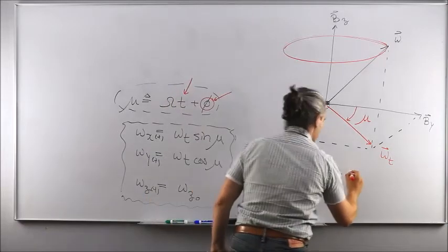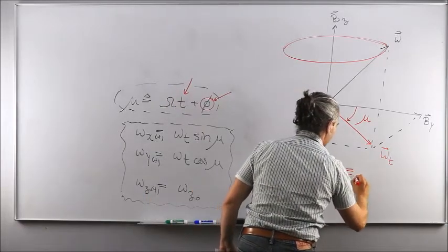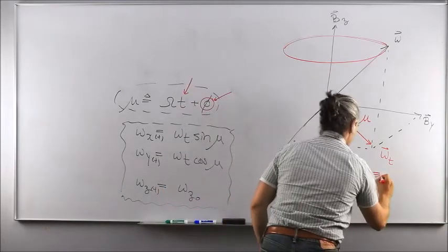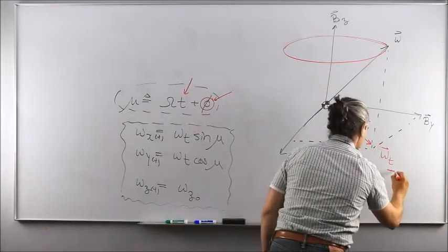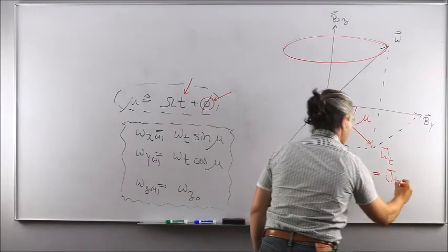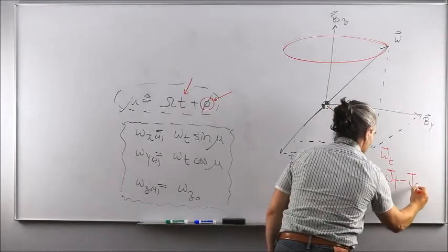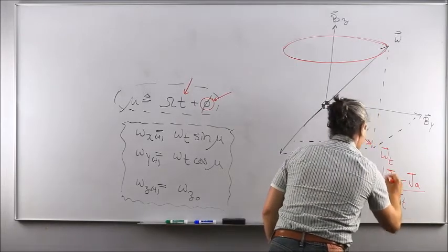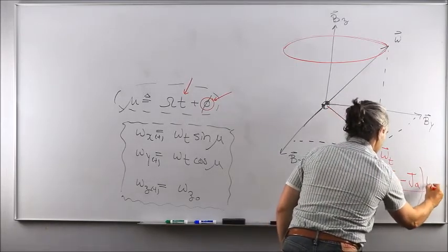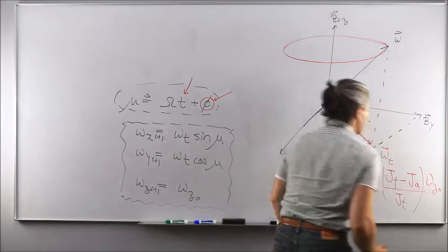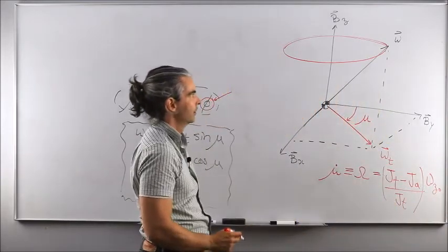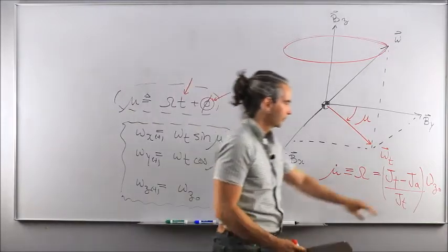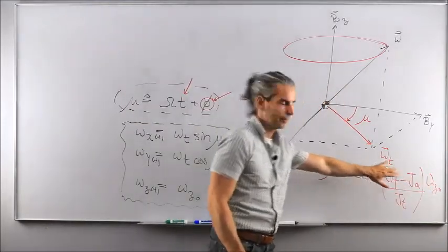And that rate is actually equivalent to the relative spin rate, which is equal from way before to the transverse principal moment of inertia minus the actual one over the transverse, and all this multiplied by the initial kick we gave to the z component of our angular velocity vector, or in other words, the initial value imposed on omega z.